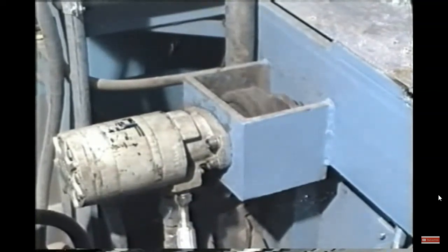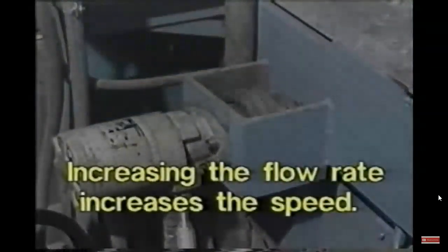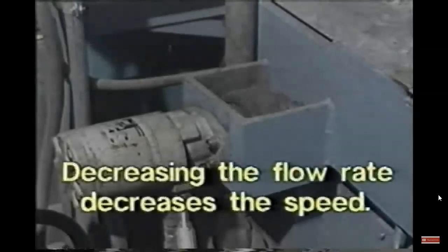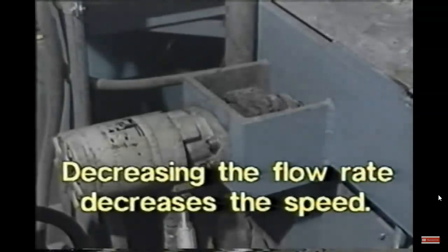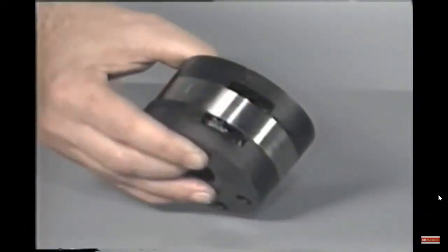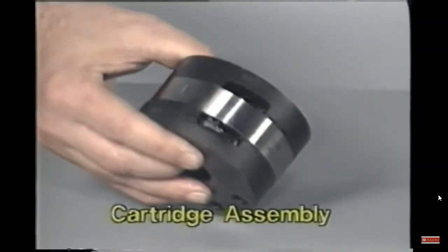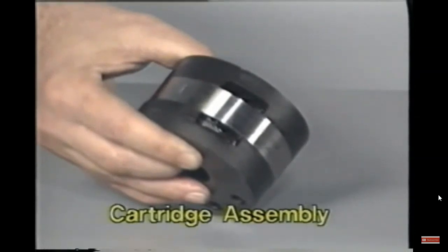Again, this direct relationship between flow rate and speed is the same for all hydraulic motors. Increasing the flow rate will increase the speed, and decreasing the flow will decrease the speed, as long as the size of the motor remains the same. The size of a motor means its displacement, or how much fluid it can hold. In a vane-type motor, changing the displacement can only be done by changing the cartridge assembly, which is the rotating group and the cam ring sandwiched between the port plates.